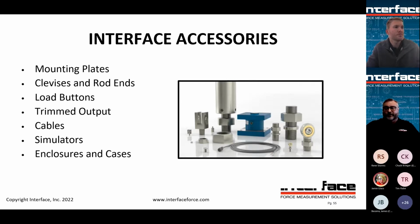Sometimes it's hard or awkward to add a lot of weight into a system, take it back out, and do that a bunch of times. Whereas a simulator, you can kind of do that with a dial, so you can dial through the whole full scale and back to zero, back and forth. You can quickly run around and check each load cell, and see if the cable's bad, or if that channel input into the signal box is bad or whatever. So simulators are super useful.